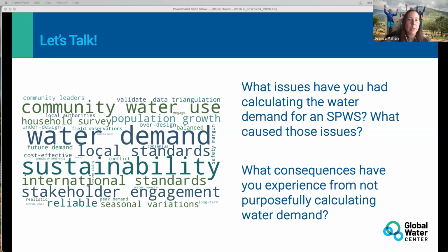And so again, that's where it comes into knowing how fast they are actually going to go through this water. And then finally, of course, as we've mentioned, budget can always be a constraint. So maybe you have to start your system off on the lower end with maybe half the daily demand, and then we can increase in a couple of years, when maybe we have some funds to add a second tank if we need one, and that can help buffer our system.